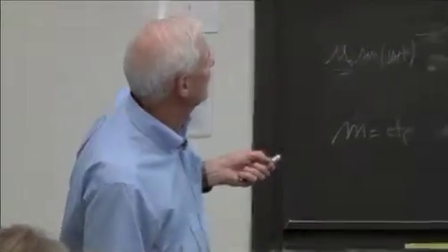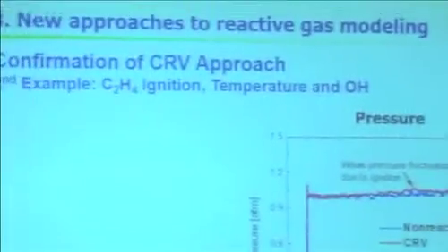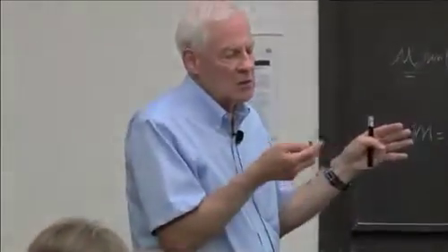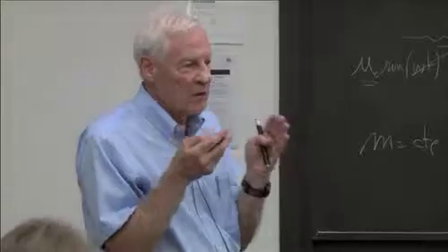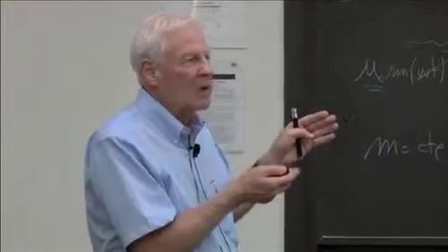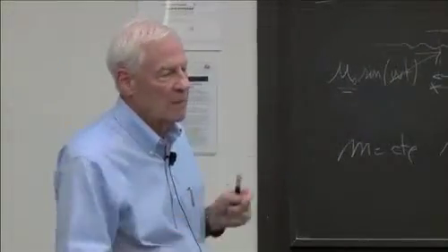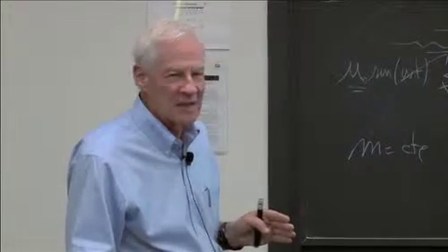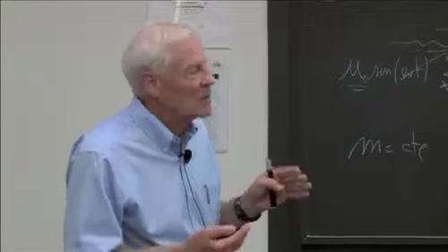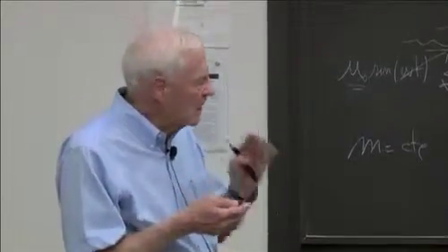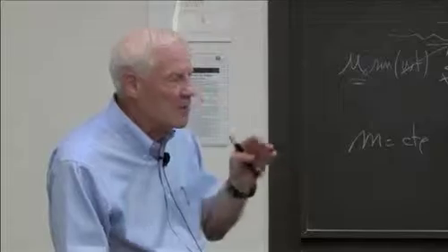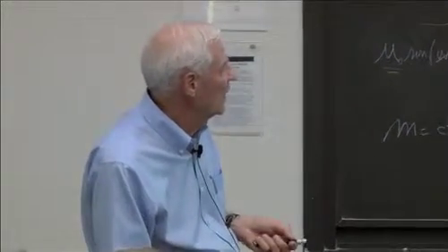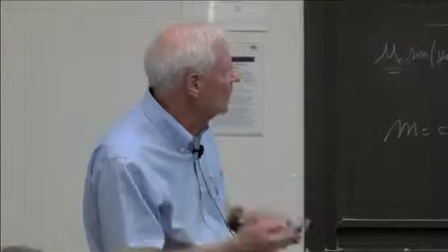This is ethylene ignition. So one of the points is, if you're a modeler looking back in history over the ignition delay times, you should favor the more recent data. The old data are more likely to have been plagued by these problems. Point number 2, everybody gets the same answer when the times are less than 1 millisecond. So the facility effects go away, and the data are good for short times. Long times, you have to really pay attention to these problems. People didn't report these issues. So the newer stuff is better. It's not all equal quality.